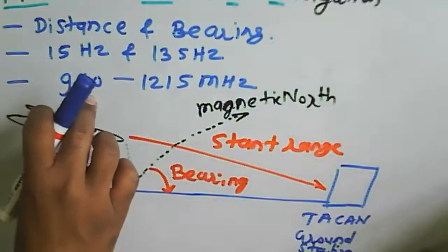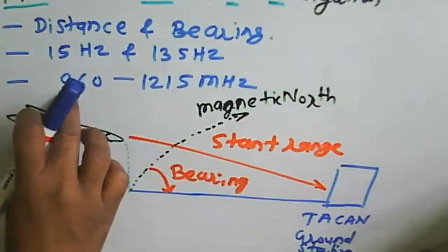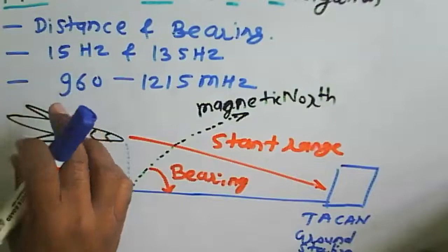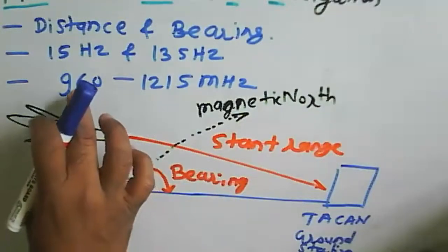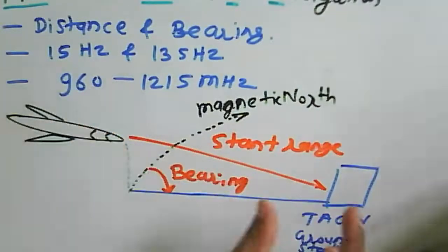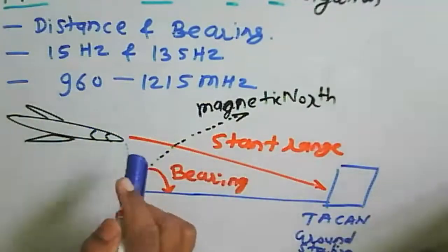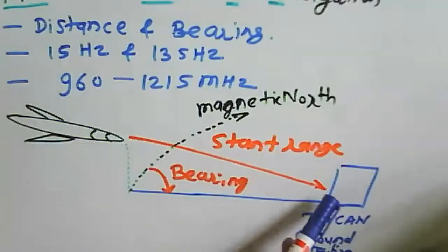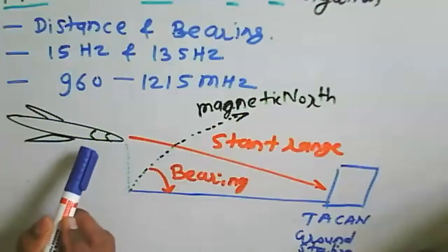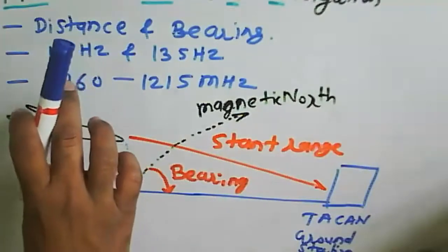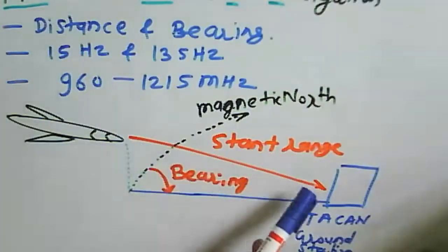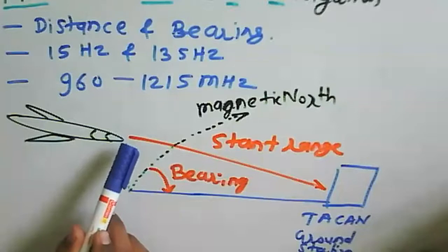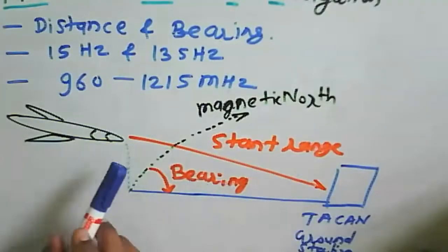The transponder will receive the signal, modify it, and then resend that signal to the aircraft. So that interrogation pulse is received here, and because the transponder is responding, meaning sending the signal to the aircraft, some delay is there. Okay, transmitting the pulse to the TACAN and then the pulse coming back, received back at the aircraft. So there is a delay. That is the round trip time, and it will be useful to obtain the distance from this military aircraft to the TACAN station there.